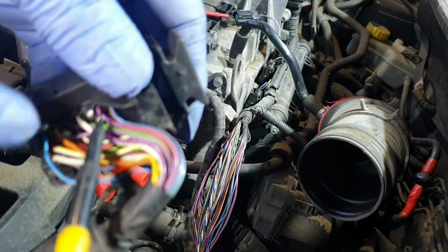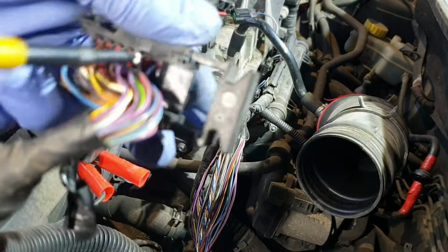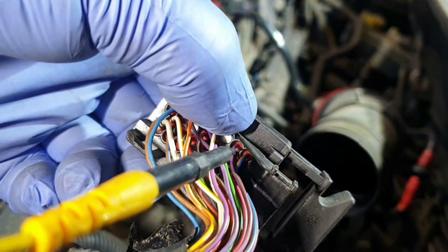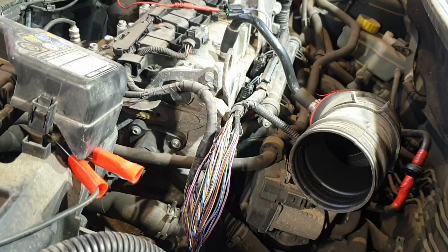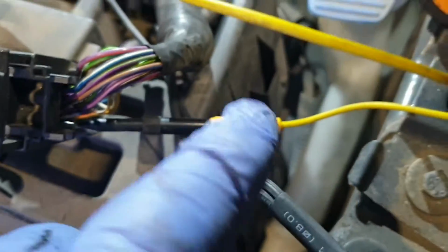and so I'm going to check continuity between this pin 79 at the ECU connector here, and the control wire of the fuel injector number 1. Okay, as you can see, I have connected this wire